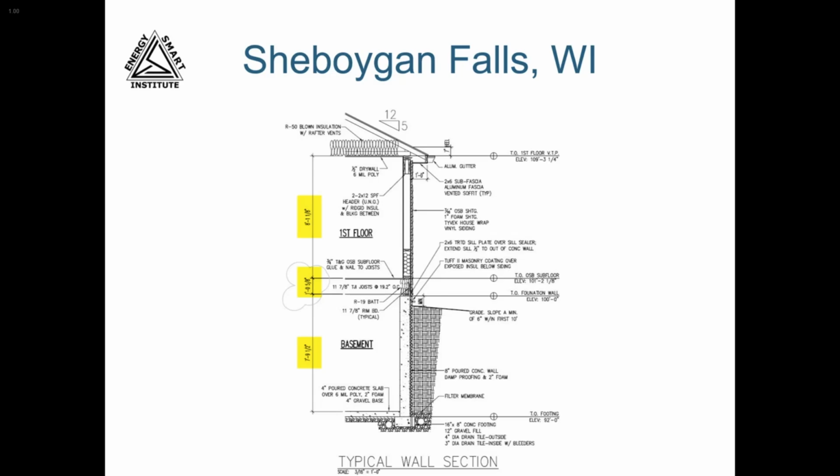ceiling. Remember, the standards tell us to round to the nearest half foot, so we're going to use 8 foot for the basement, 1 foot for the joist, and 8 feet for the first floor. Write this on the plans so you can defend your calculations later if you need to.